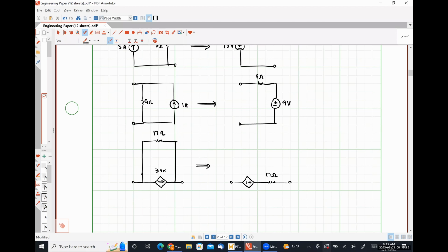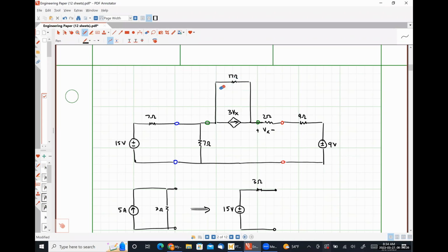I'm simply going to multiply 3 amps per volt, that's the units here, right? Times 17 ohms, which is 17 volts per amp. And so 3 times 17 is 51 Vx. Even the units work when I do this, right? So I'm going to disconnect this guy here.